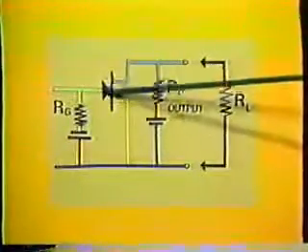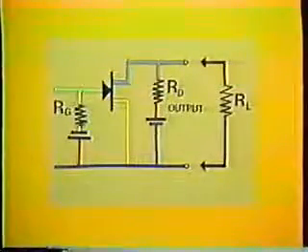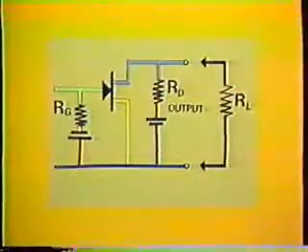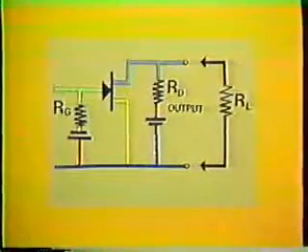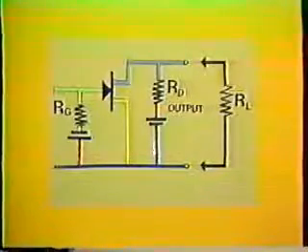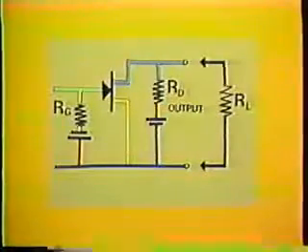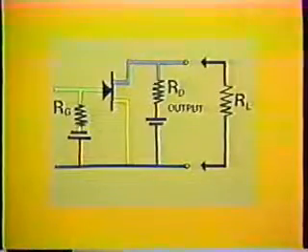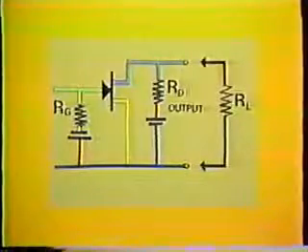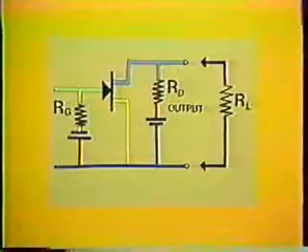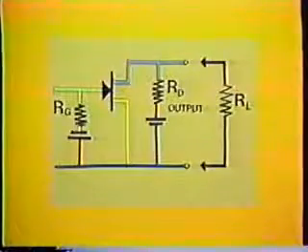This is a typical small signal amplifier circuit using an N-channel field effect transistor. Amplifiers using field effect transistors have extremely high input resistance, often several million ohms. Because of this high input resistance, they are often used in electronic meters and instruments. Field effect transistors are also low noise devices, which makes them useful in stereo and hi-fi applications and in medical electronic circuits. This concludes Chapter 7.